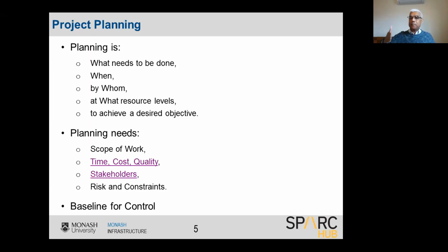So you will have multiple plans. You have the original baseline, then after a week or two, you will have a new program. And then when you go to the next month, you will be comparing that work against the new baseline, as well as against the original baseline. So the plan, the baselines and the control are an iterative process. You compare and contrast and do the control measures. That's what the planning exercise is.